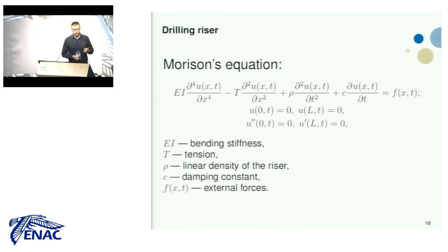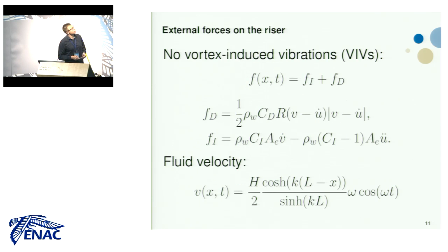For the oil companies, it is very important to predict the fatigue of the riser at the seabed, where it is connected to the wellhead. The riser motion is governed by this partial differential equation, which includes the stiffness, the tension of the riser, its linear density, damping constant, and some external forces that, in our case, model the eddy waves. Once again, they are used in the case when the seabed is flat.